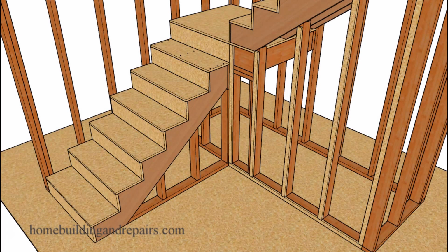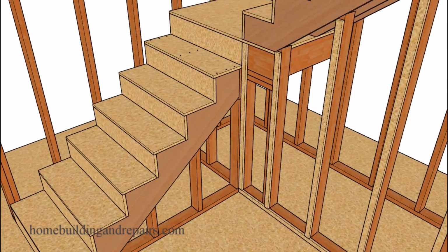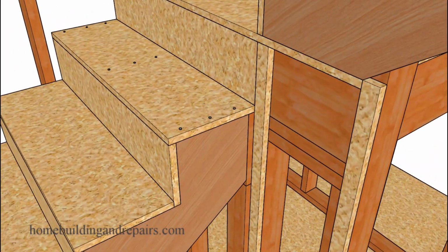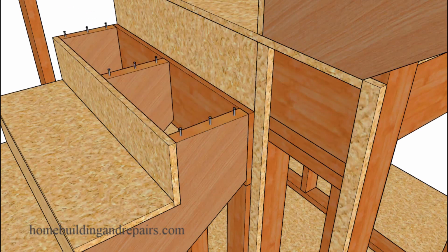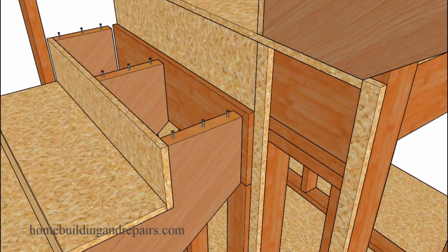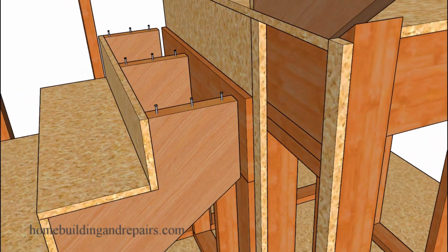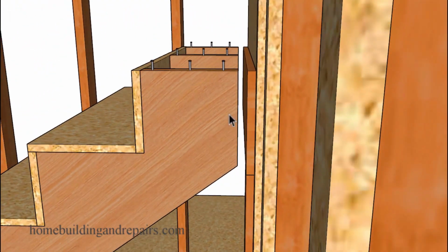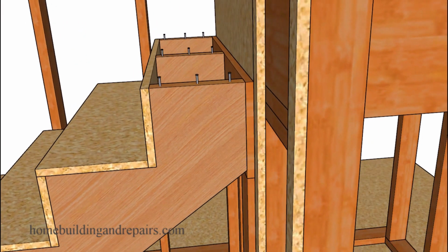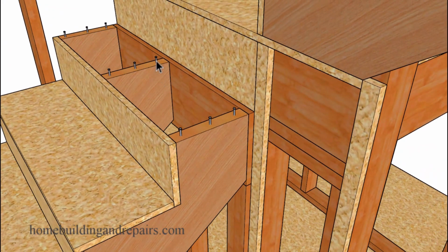here is another quick tip I would like to throw out there for stair builders who are looking for a little stronger connection at the top up here, where the last tread can be used to prevent the stair stringers from separating from the ledger. Now, obviously, this is a little extreme here, so let's go ahead and put that thing back together. And this is normally how it's done.